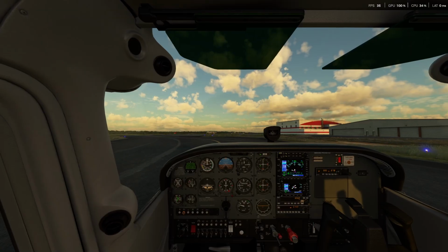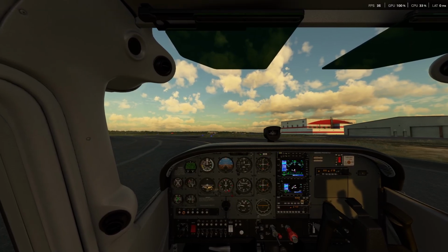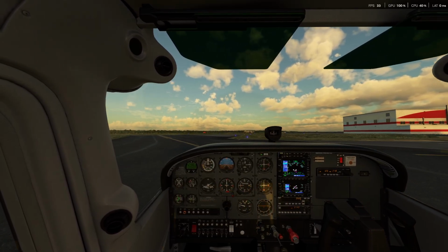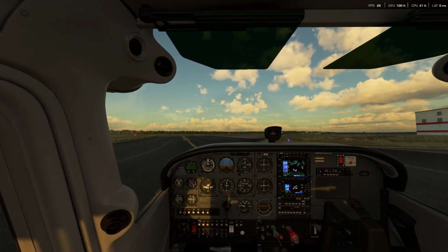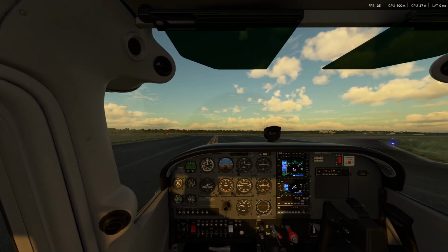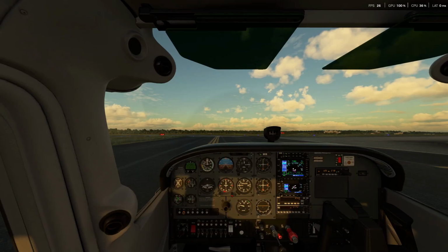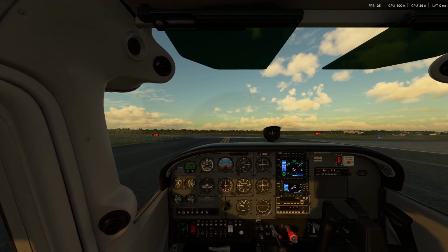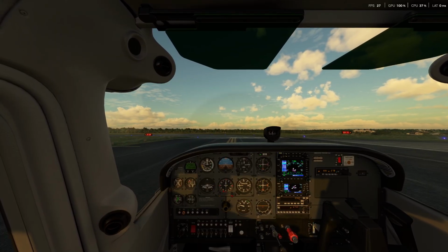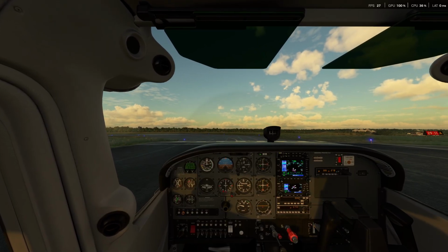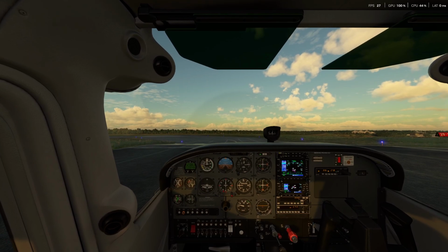And some further departure brief. The routing, again, we plan to take the Notre Dame departure. It's going to be a right turn off of runway 29. However, the tower could change that, but again, the tower's not online, so we'll disregard that point. For the altitude, I'm planning the initial climb to about 1,500 feet as per the CFS Notre Dame VFR departure, until we're clear of the Class D control zone here. So I'm going to stop right here and we'll finish out the checklist.